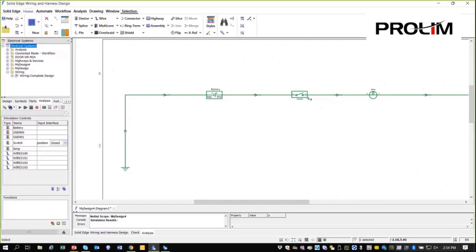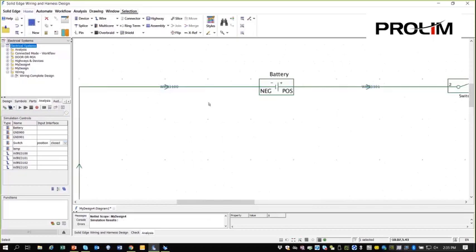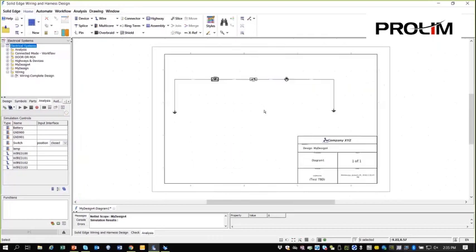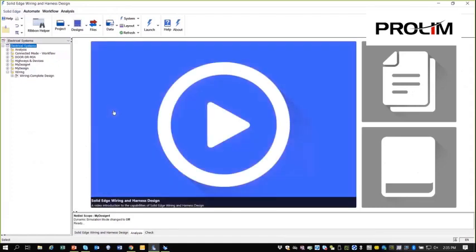Right? We can do the same thing in the graphics itself. I want to show you the current reading. We would change to numeric simulation, wait for the green, and then just hold our cursor over there, and now we get the current reading in there. So the users could go in, change the wire diameters, see if they're getting the performance that they want, and they can do that. This is a pretty simple little example. I have another circuit that's a little more detailed than that, which works for us as well.